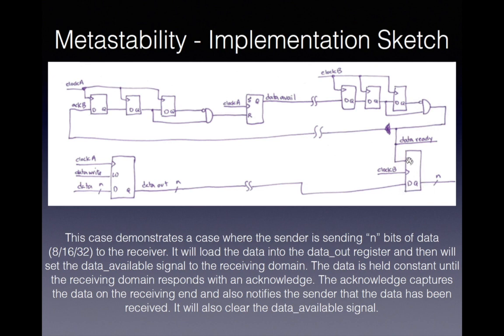So what this diagram is meant to demonstrate is that when you're synchronizing control signals that are controlling the movement of data, you do not need to synchronize the data path. It's only the control path that needs synchronization.